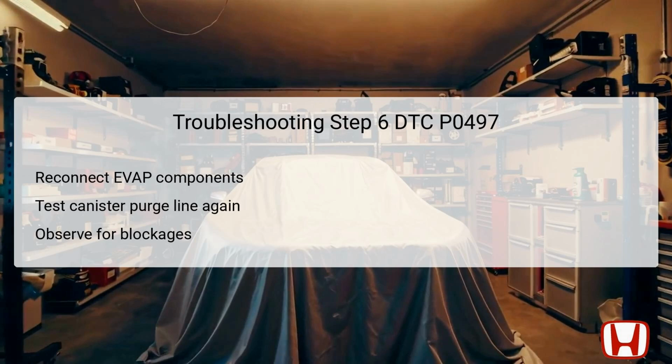Then, operate the HDS by engaging the EVAP CVS on function in the single solenoid. Slowly apply approximately 2 kilopascals of vacuum to the line to evaluate if it maintains vacuum integrity. If the line holds, look for any blockages within the EVAP canister purge line port. If it does not, the EVAP canister vent shut valve may require replacement to restore proper functionality.